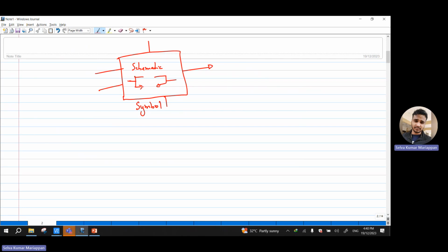So for the schematic here, you don't create a new cell view. You have your library, you have your cell view, and then you have your view. Let's say your library name is X, your cell name is X1, and here you should have your schematic, and then your spectre state you saved, and you will have your symbol here.